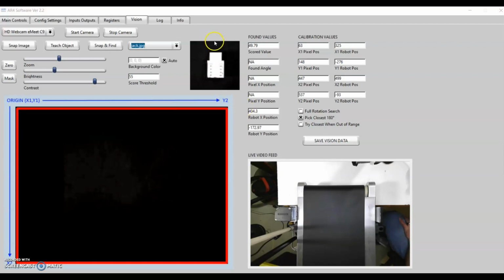The found position is a rotation of axis 6 when it returns this angle. If you're trying to pick at a specific position, you might have better luck if you teach the pick with the part at the robot's axis 6 0 position.